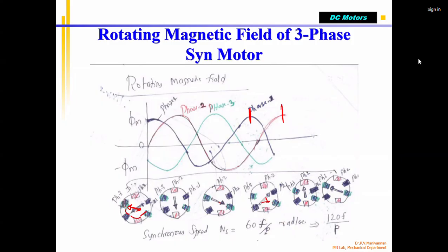So you can see that continuously, because the AC voltage, which is sinusoidal in nature, all three are equal strength, but they are separated by 120 degrees. And the resultant magnetic field which attracts the rotor is passing from one pole to the next pole, next pole, like this, correct? So within 2 cycles, the rotor would have rotated 360 degrees. Correct? So this is how the rotation works.